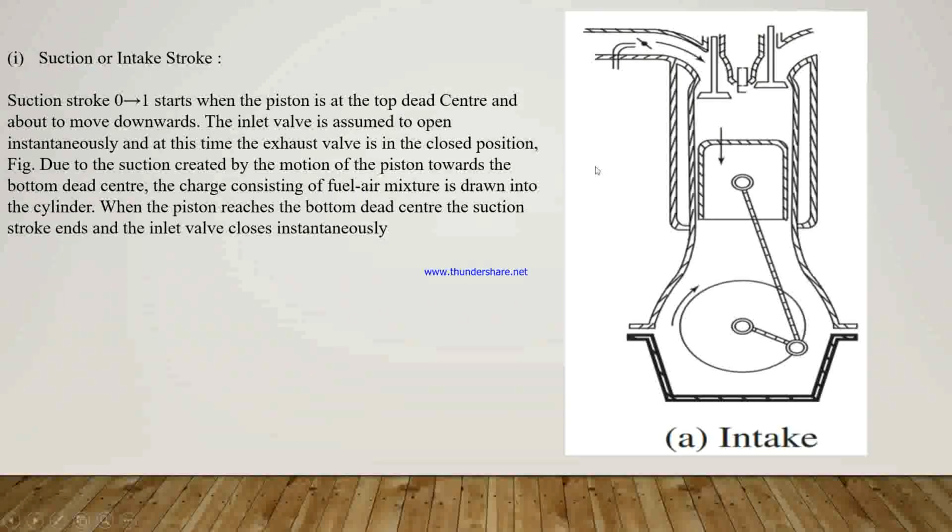The suction stroke starts when the piston is at top dead center and moves downwards. At that time the inlet valve opens instantaneously, and the exhaust valve is closed. Due to this suction, there is a motion of the piston towards the bottom dead center.